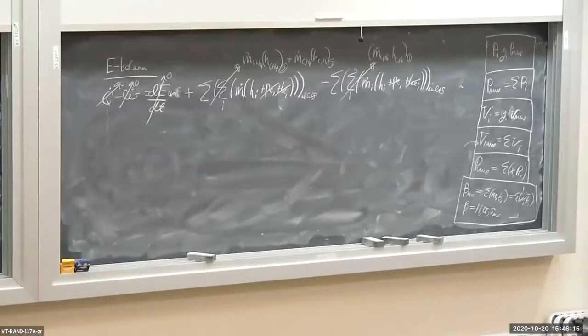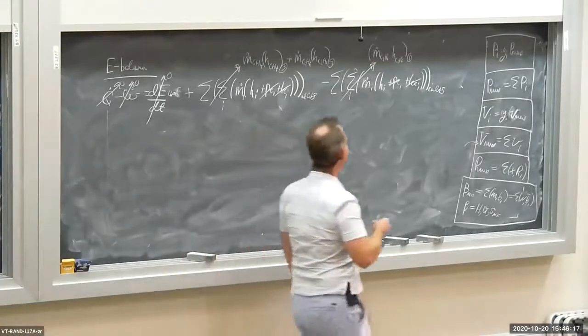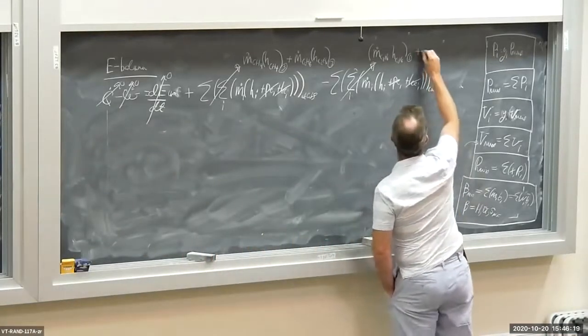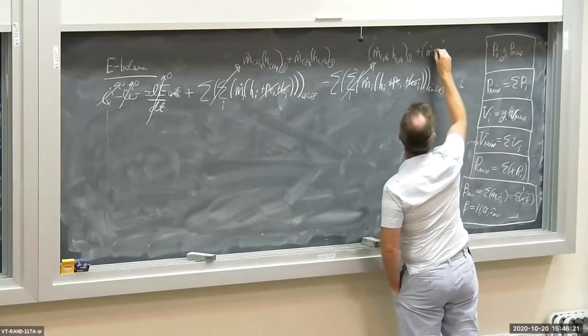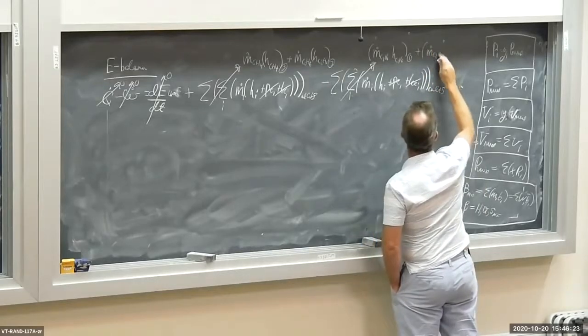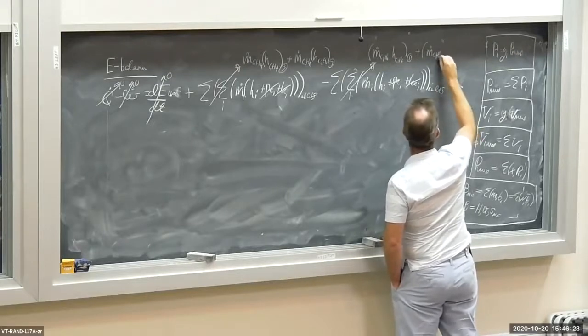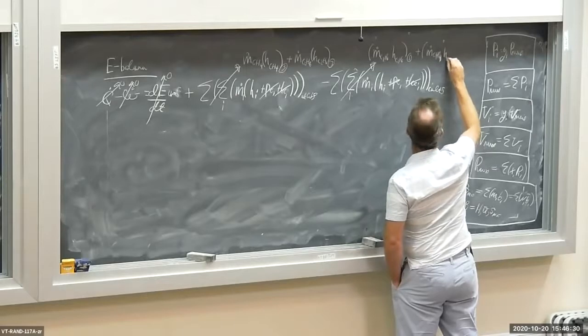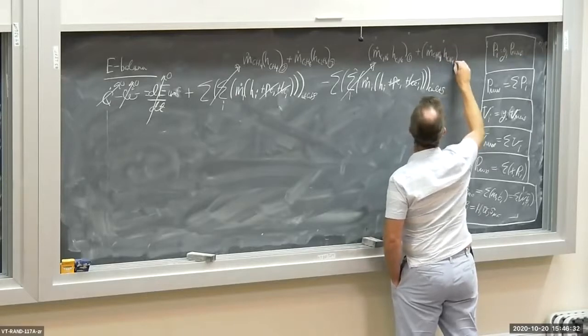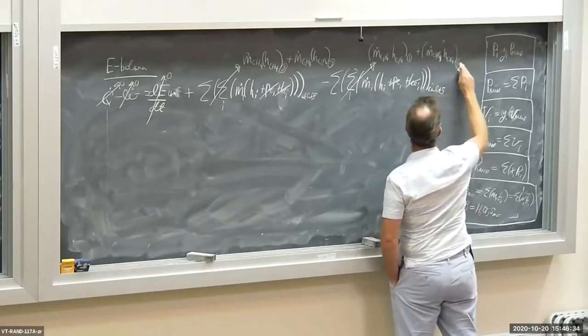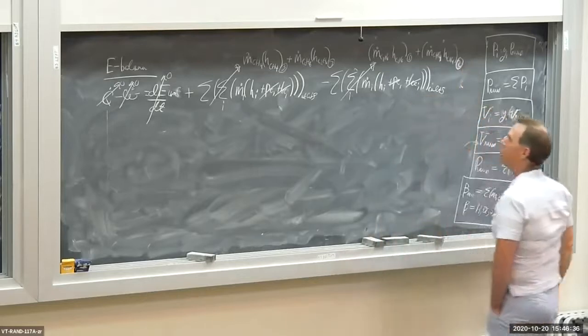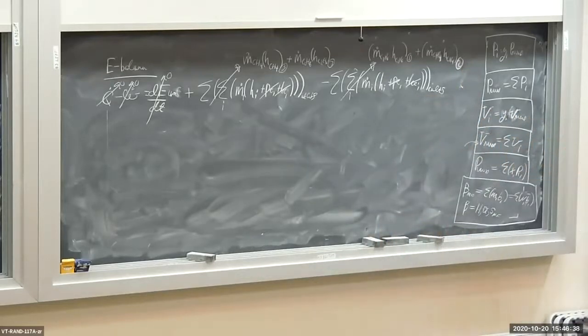And port number 2 is where the methane comes in. So I'm going to add on the enthalpy flow for the methane, m dot CH4 H CH4 evaluated at inlet port number 2. Okay?